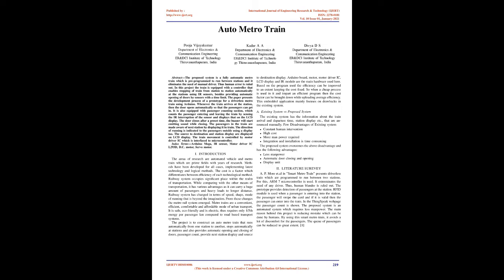3. Experimental procedure. The following innovative measure can hereby be introduced in the construction of RCC slab culverts, bridges, bathing ghats, and construction of all civil works nearby seashores and other places, also using plastic wastes collected in rural areas. 1. Dig the foundation to a depth of 1.5 m and above. 2. Remove earth nearby the foundation. 3. Collected plastic waste bags from the respective panchayats and nearby panchayats are stacked by volume of 1/5 of the M.Sand, or sand volume of the drainage layer, prior to the PCC.